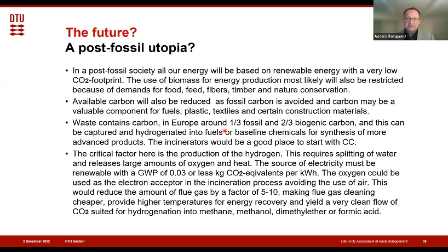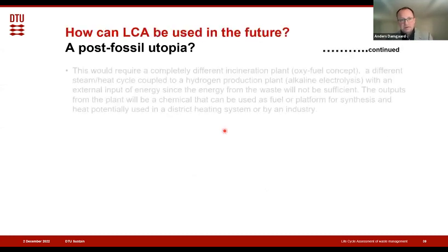That will give us less flue gas produced, because now we have less other gases going in, so it will just be the pure combustion. And it also means we have the heat, and if we have a waste-to-energy plant, where in Denmark we have district heating next to it, well, then we can use the heat very efficiently.